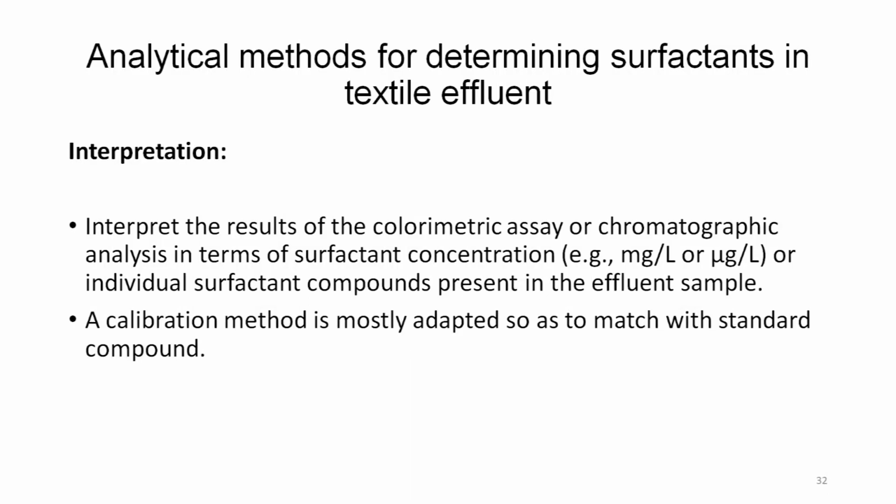Interpreting the result of the colorimetric assay or chromatographic analysis in terms of surfactant concentration, that is milligram per liter or microgram per liter, or individual surfactant compound present in the effluent sample can be done. A calibration method is mostly adopted so as to match with the standard compound.